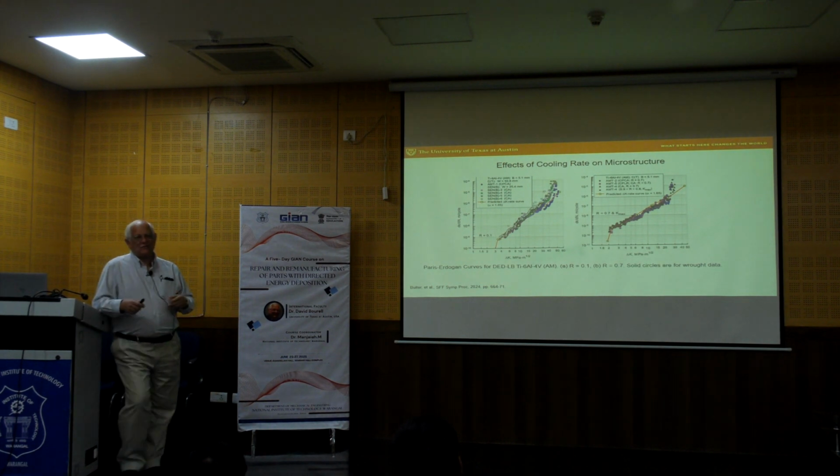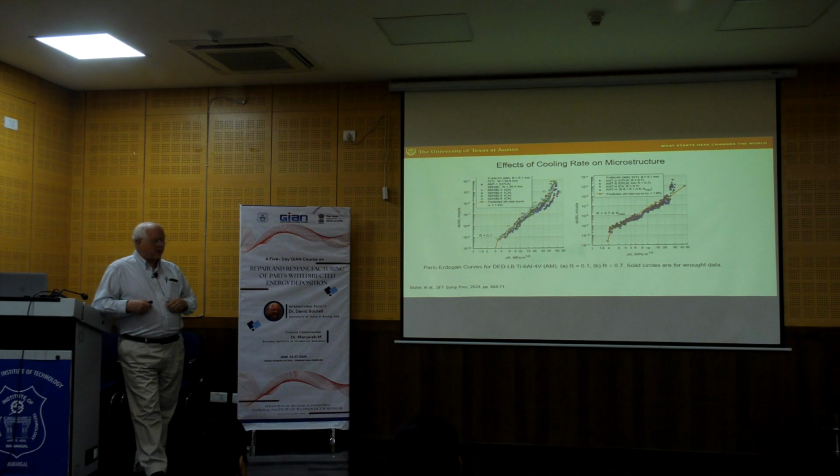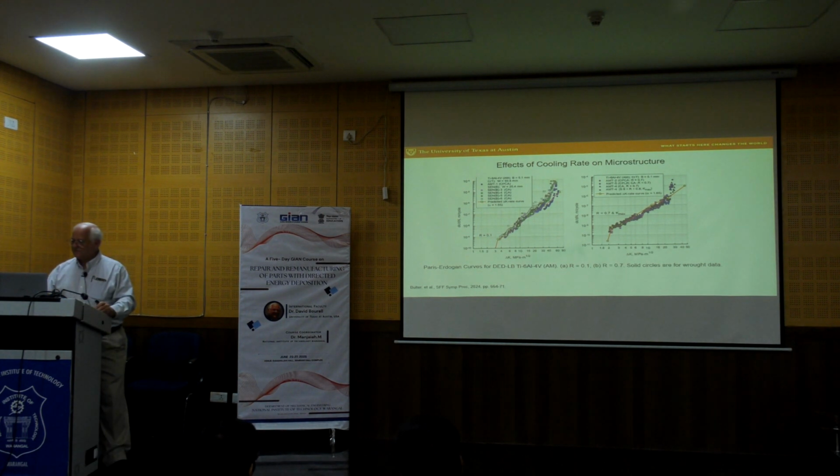So again, the bottom line theme of this lecture is if you use best practice and do a really good job controlling the defects, the porosity particularly, or if you do post-processing to control the porosity, then we can get parts that have mechanical properties that will rival conventionally manufactured parts, say by forging, which would be the case here, or rolling. Okay.